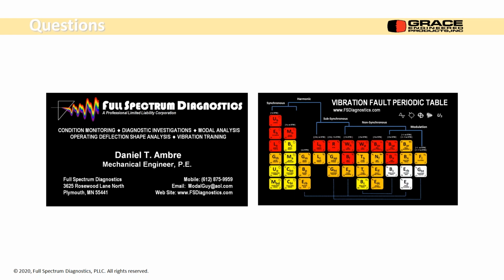Okay. What are the possibilities to not only diagnose existing problems, but forecast the failure based on trends? That's how we do it now. Everything's a trend. You're looking at how things progress. And this last part of the presentation on having a transducer that's in place at all times and it's taking data at a much higher rate than just the route-based guys, you're going to get a really good trend.